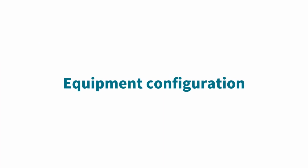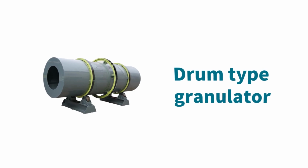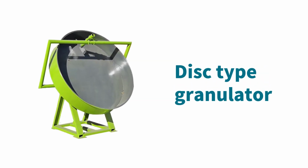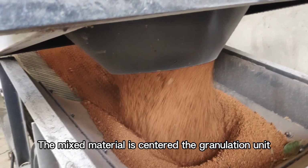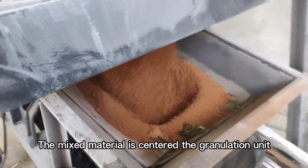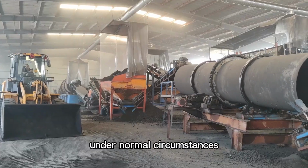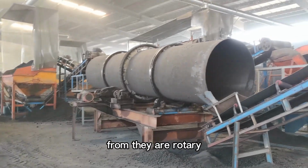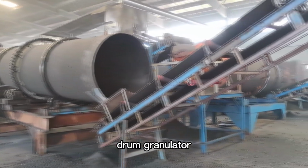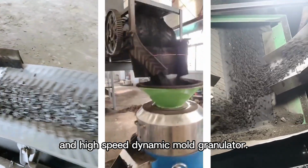The granulation section. Equipment configuration. Drum type granulator. Disc type granulator. High-speed dynamic mold granulator. The mixed material is sent to the granulation unit through the belt conveyor to make granular organic fertilizer. Under normal circumstances, there are 3 kinds of granulation process to choose from. They are rotary drum granulator, disc granulator, and high-speed dynamic mold granulator.